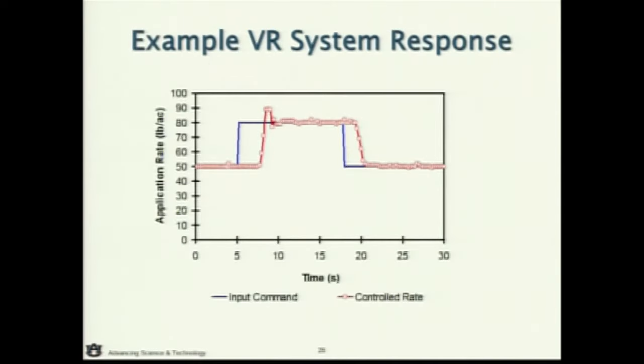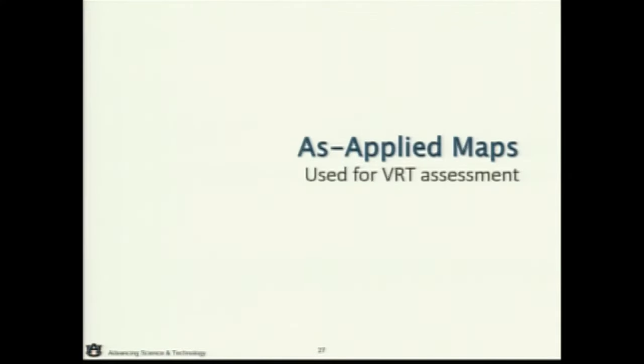systems. So with that, the last thing I'll say about that is not everything happens instantaneously, but there's a benefit in most of these systems to set what we call a look-ahead time. We just shift to make sure that rate change occurs. So again, a look-ahead time is a value. Typically in most of these it will be somewhere on the order of a half second to 3 seconds, depending on the implements. And most of your dealers or equipment companies can really help you know what that value should be.